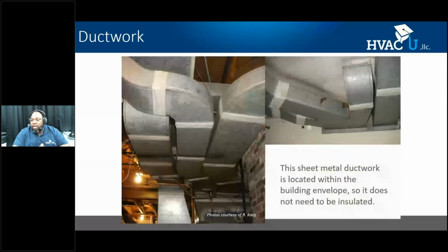All right. Now, when we seal the duct system, there's a few different options. You have your mastics and your tapes. You even have specialized solutions like AeroSeal, which can seal the ducts from the inside. Regardless of what your duct system sealing type is, the key is to seal the ducts regardless of where they're located, if they're sized properly.